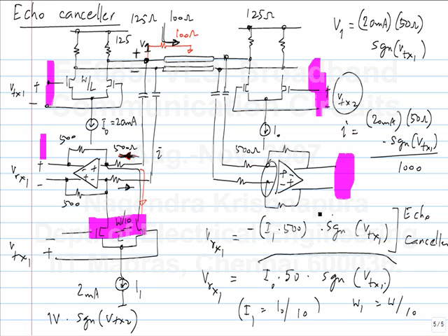Then, resistor variations: there will be a random mismatch between resistors. Is that the only problem? There will be random mismatch, but the important kind of mismatch we have to be worried about here is that the left side is one chip and the right side is a different chip. Now this whole scheme relied on looking at 100 ohms into this transmission line. That means all of the resistors on this chip will present a 100 ohm impedance. So mismatch between two different chips is even more. There is mismatch on this chip, and mismatch between this chip and the other chip.